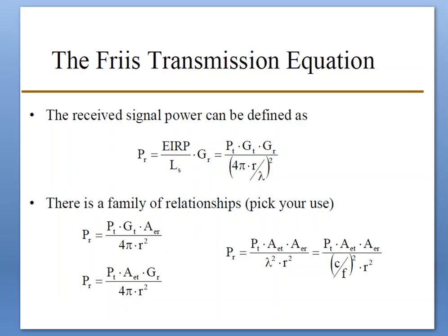Of course there is not. The equation seems to be constant only because antenna gain and antenna area are stated along with wavelength in the equations. We should choose one of these equations for determining the receiving power as a function of wavelength. Considering a system already configured, where the antennas have been built and other dimensions are fixed, the equation is the appropriate choice for calculating the receiving power performance for fixed-size antennas, and the receiving power increases as the wavelength decreases.